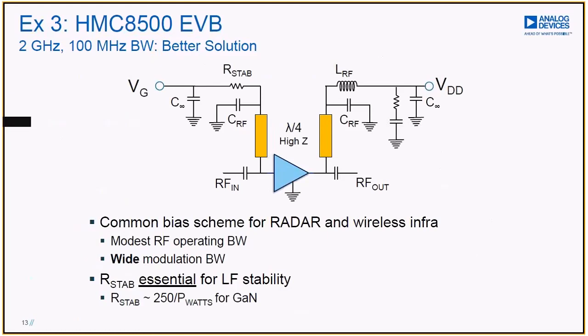Couple of ways you can do that. You can either lower the value of that inductor, or you could do this. You'll see this circuit very, very commonly used in wireless base stations, radar systems, and so forth. This tends to be a narrow band solution because we're pushing the bias through quarter wave stubs there. But for 10, 20% kind of bandwidths, this is a perfectly wonderful scheme.